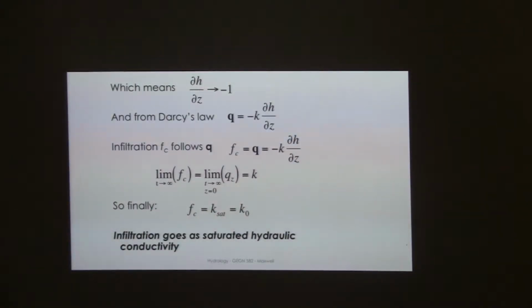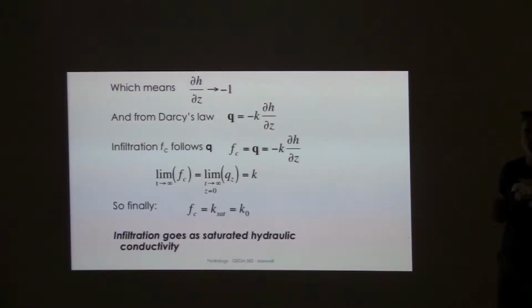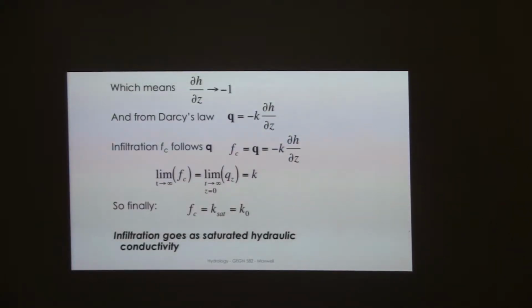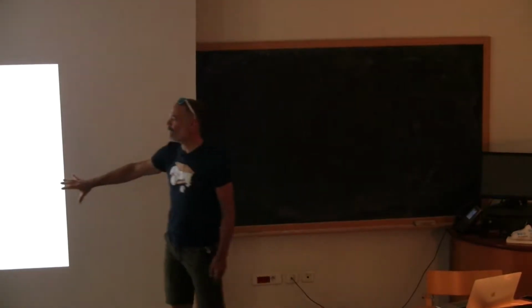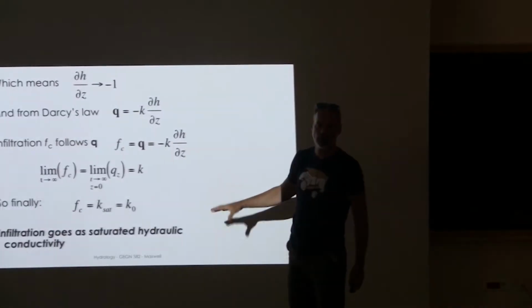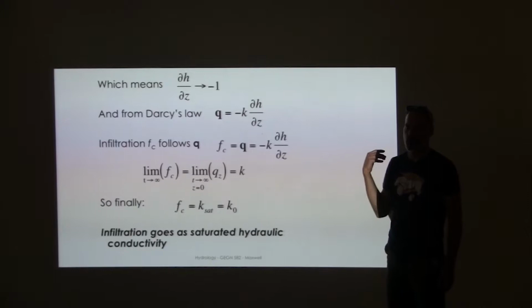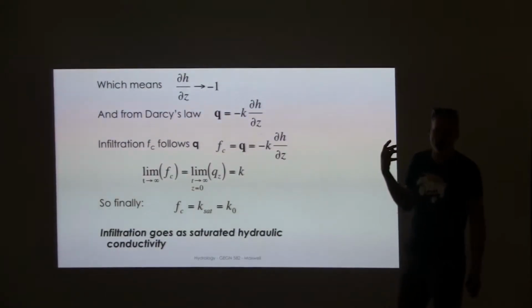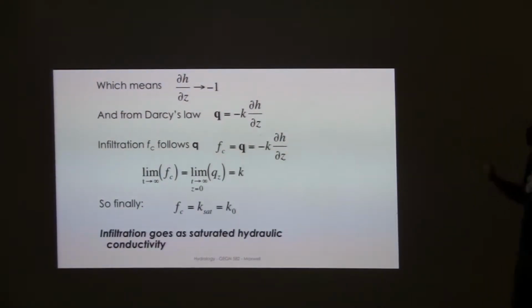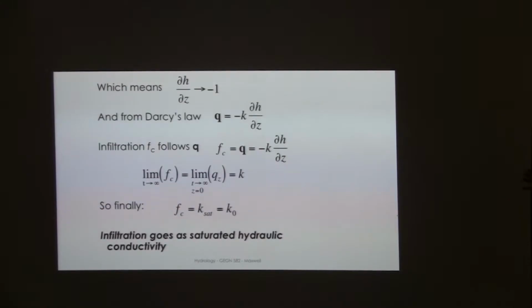So this means, very simply, that saturated hydraulic conductivity over the column, given all these conditions, saturated hydraulic conductivity is our lever. That's our knob for how much infiltration enters the subsurface versus ponds. OK, so that's a pretty simple concept. It's really kind of hydrology 501, if you will, right? Usually graduate level, but pretty basic. All right, let's put that aside for a second.